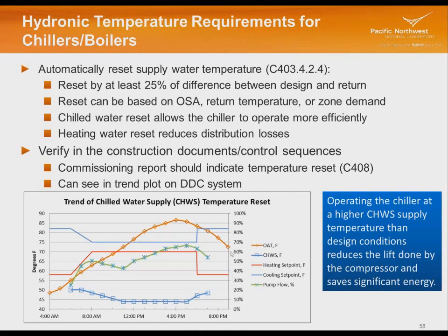Because of that, we should have very little operation of our systems during the night. But if for some reason we got too warm or too cold, the systems can turn on automatically and keep things from getting too out of hand for the morning. Then, depending upon how hot or cold it is outside, we would start to bring the set points down. That's called optimum start.